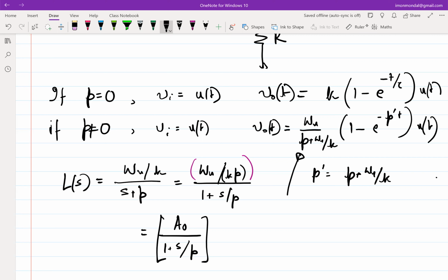Okay, so essentially at omega less than omega u over k, I know that by definition, mod of L of s is greater than 1. Which means below omega u over k, which is the unity gain bandwidth of the loop, your feedback works. And above omega u over k, when the loop gain falls below 1, feedback doesn't work. Or rather, simply say feedback breaks, which means that the loop doesn't exist anymore.